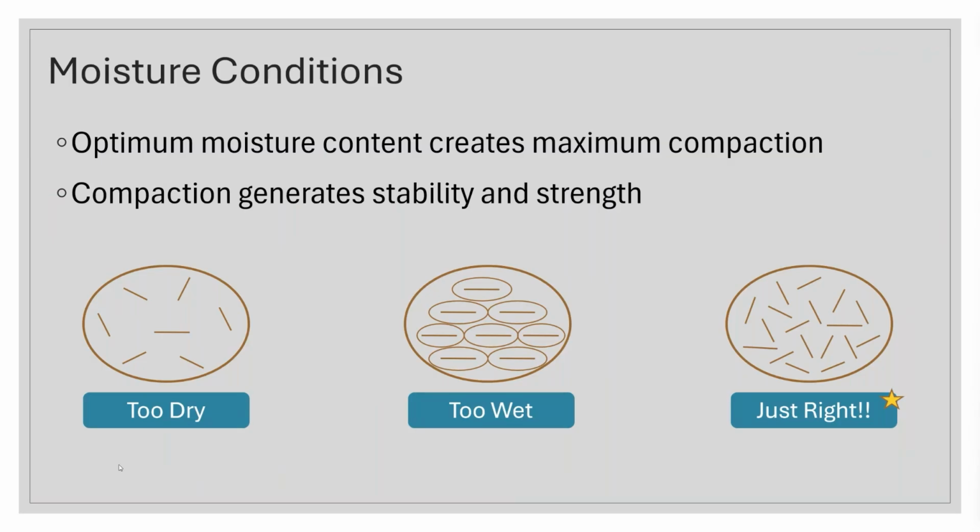But whatever the soil type is, we're also going to figure out what is the moisture content that gives me the best compaction properties. So if we say we have a handful of soil, it's very dry, very powdery, and I try to squeeze that. Think of our squeezing being the same thing as compacting it in the field. If I don't have any moisture, it doesn't really hold together. There's no cohesion. It just sort of moves around, but it's not super tight. I'm not really able to squeeze that. So if we look at those individual little particles, when it's too dry, you're going to see those like in the little diagram to the left. It's got random arrangements of particles.